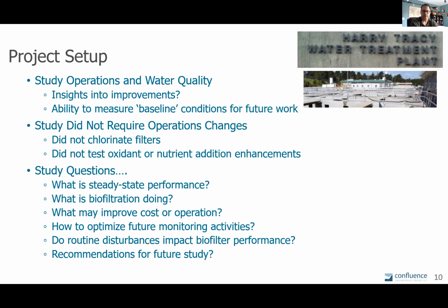We monitored the filtration process, of course, and before and after chlorine contact and into the distribution system as well. And we looked at a lot of these parameters on the left in the text here: chlorine residual demand decay, oxygen, ORP, a lot of metals, microbials, organics, and others.